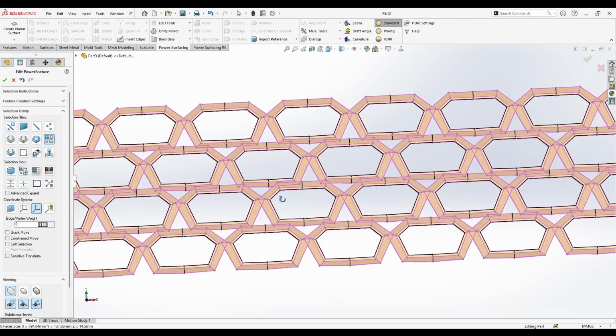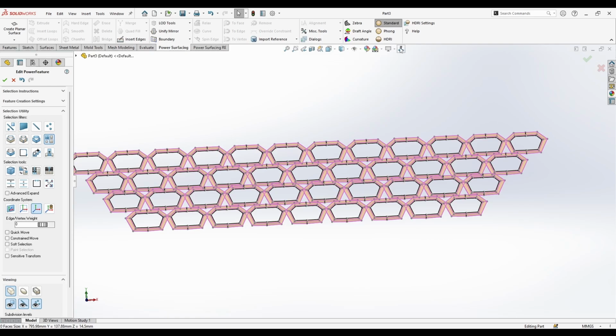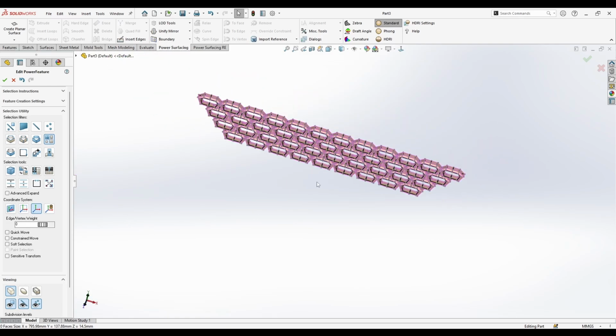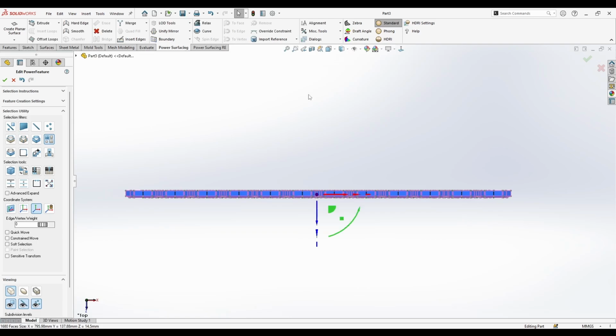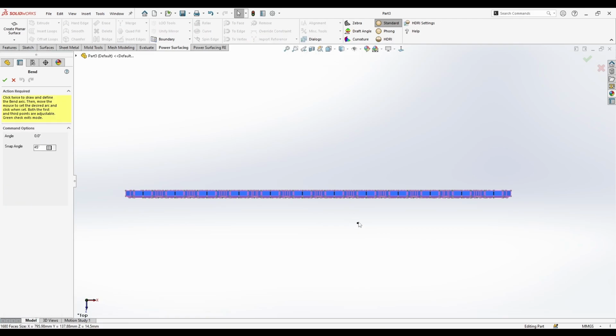Now what we're going to do is use the bending feature. In this case there's no mirror, so if you just go to bend from the mesh tools, select them all, and go to bend, you can see here, I just choose the center of it, from that one to up there, and I can make a little bit of angle here.